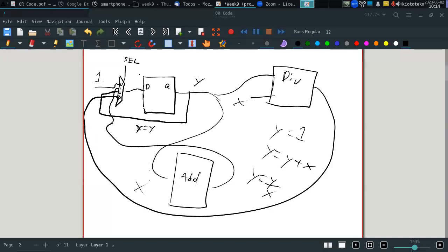But again, as we were talking in this section, in our new designs we have a separate control circuit and a separate data path circuit, no? Which is this one. This is the data path circuit. And we need to design a controller circuit that controls these select signals, because we will have many multiplexers. That is the separation we do in order to facilitate our lives while designing these circuits. Any other question?